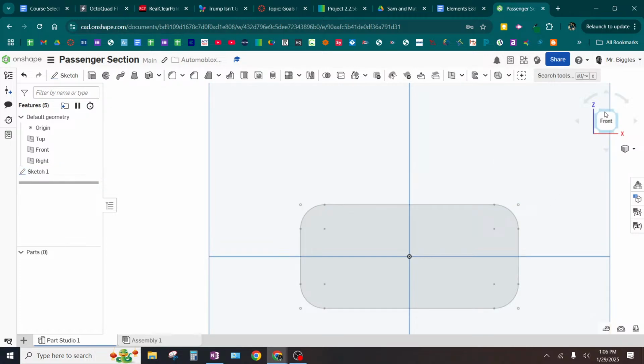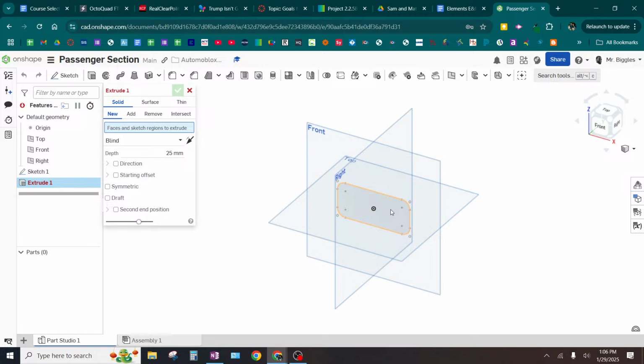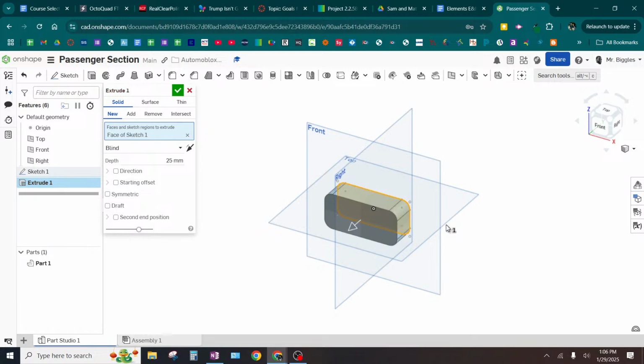All right. Well, you can now extrude. You should know how to do this. One mistake I see a lot of people make is they start trying to draw this cavity. But does this cavity extrude all the way through? No. So it's not part of this. If you have 2 different things on the same surface, but they don't have the same height or extrusion depth, don't make them in the same sketch. Most of the time, you want to make them in separate sketches.